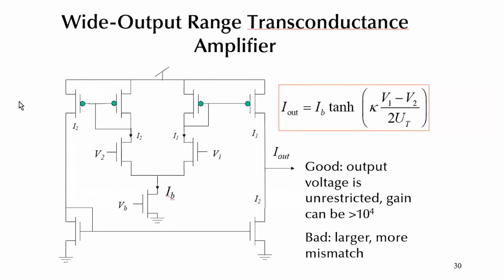And so next week, we're going to talk about linear systems. That means we're going to look at how the signals change as a function of time whenever you change one of the input voltages. Right now, everything's kept constant, but what you want to see is, if I change V1 all of a sudden, like a step function, for example, then how does the output voltage change as a function of time? That's always interesting because it's going to depend on, again, the current to the bias transistor. You probably will have to hang a capacitor here, right? So you can talk about filters, first order filters, second order filters, and so on.